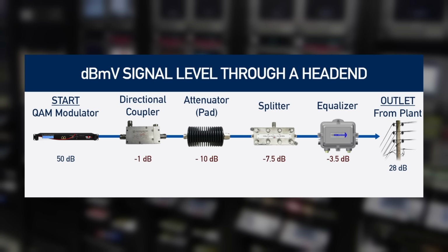If I were to plumb this into a TV right now, it would more than likely fry its tuner due to how high it is. When this hardware is used in a head end, 50 decibel millivolts would be fine for distribution since there's going to be long runs, splitters, and other hardware on the line that will knock it down along the way. For our use though, it's at least 5 times too powerful.